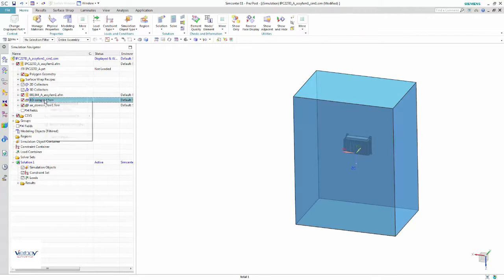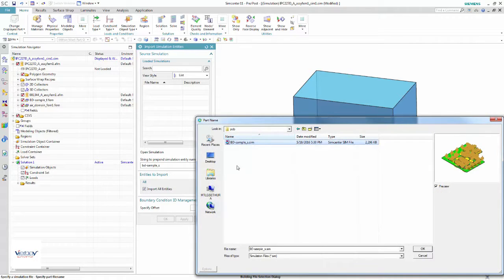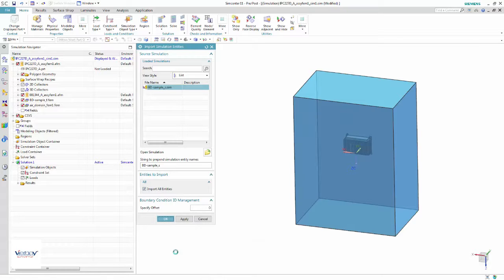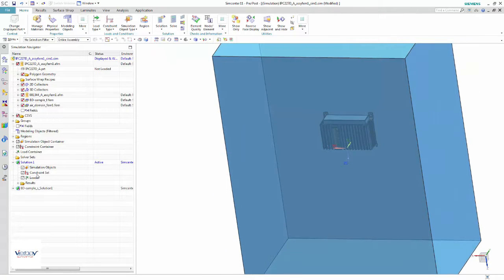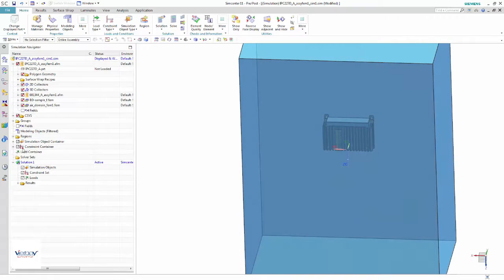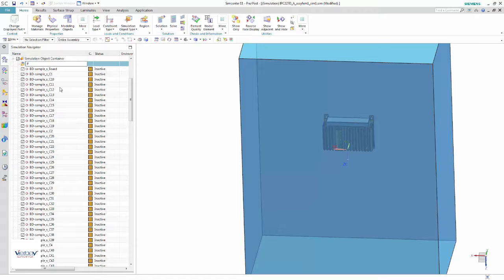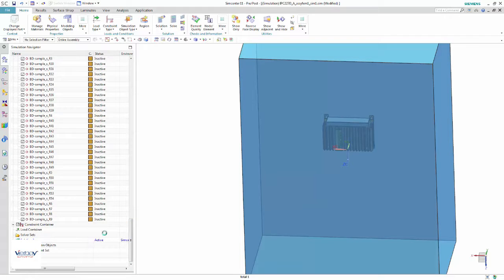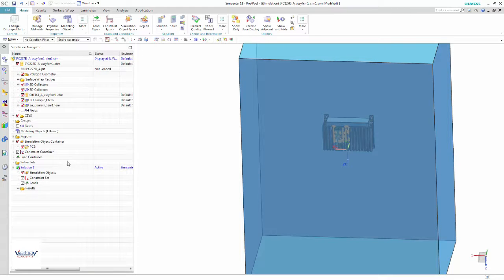Because the CAD model for the PC chassis is an assembly, we can quickly reuse existing boundary conditions. Here we can import previously defined boundary conditions for the PCB into the entire AFEM. This greatly reduces pre-processing time by not having to redefine loads and boundary conditions at a new level. To ensure that we don't unnecessarily clutter the simulation navigator, we can also quickly do some bookkeeping and select all the different entities we've just generated and put them into a new folder.